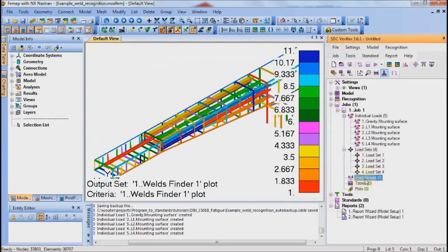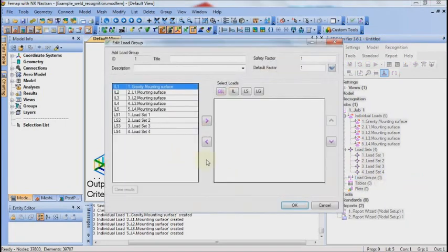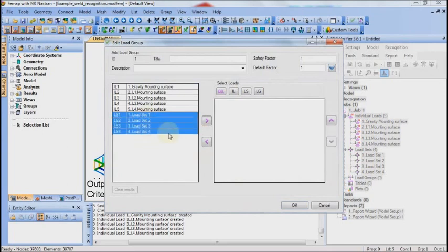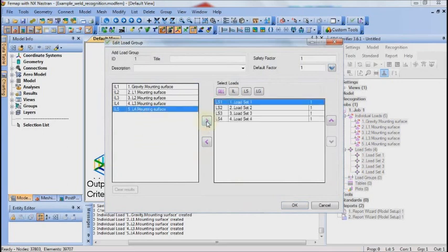and for the fatigue calculation we need to define all possible load situations. Remember that for fatigue calculation it is not only important to find the maximum results, but we focus on the stress difference, and for the stress difference you also should watch for the minimum load set.